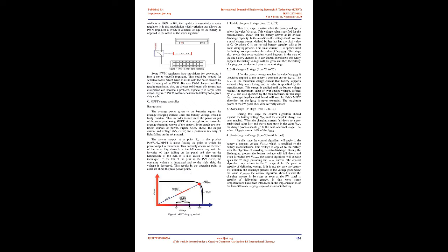At 30 degrees Celsius, the self-discharge increases, and recharge will be needed every 6 months so that the battery does not drop below 60% for some time, which causes sulfation.